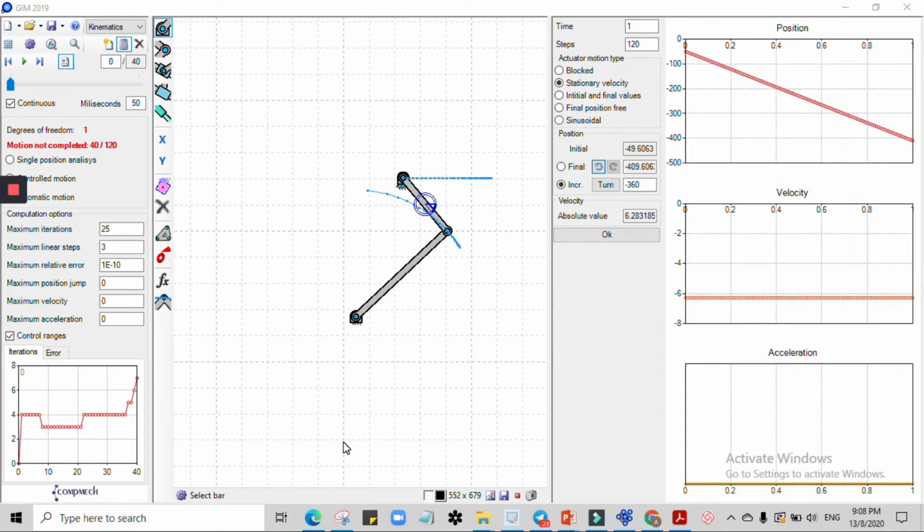For the conclusion, the Gym application is very useful for doing the simulation and very helpful for finding the mechanism movement, and velocity and acceleration can be obtained and depicted as the motion is performed. Also, graphs and tables with this data can be plotted. Every kinematic construction can be demonstrated: instantaneous center of rotation, speed and moving polodes, acceleration pole, acceleration circle, and so on.